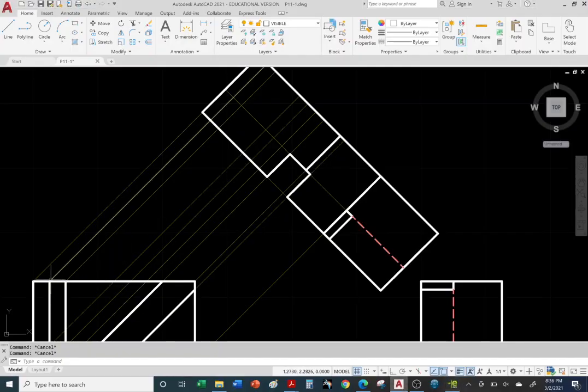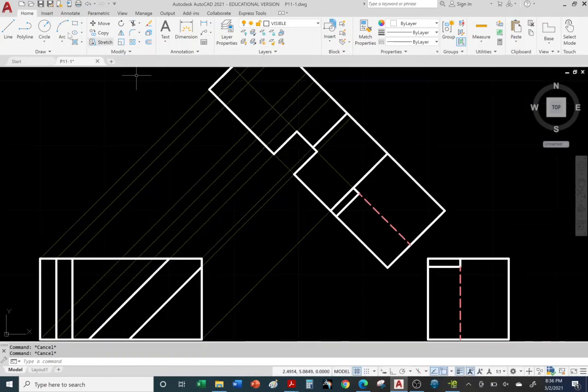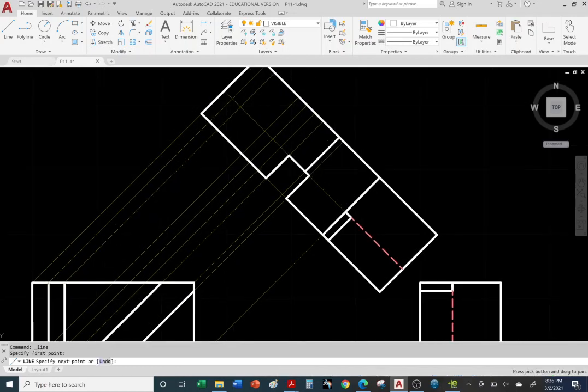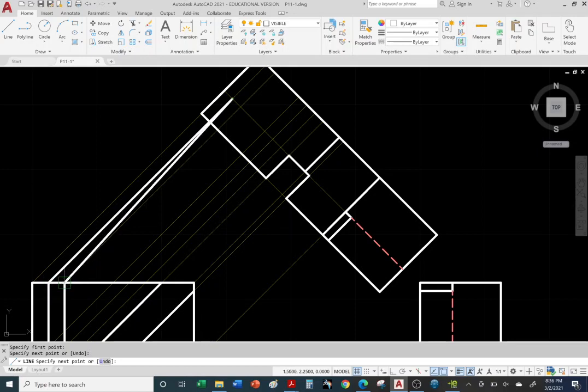Okay, so we're going to come over from the front view. Let's use the line command, white visible object layer. From this corner, we're going to follow the yellow construction line, follow the yellow brick road, right click. And we know that this is the size of the opening. So we're going to follow this construction line, right? Follow it. There it is, and close it.